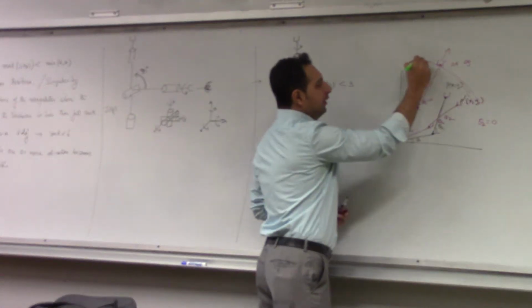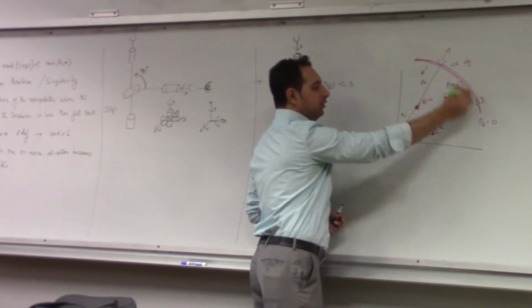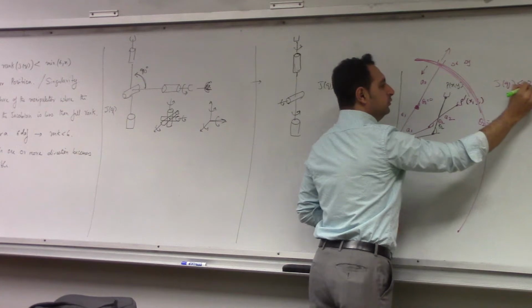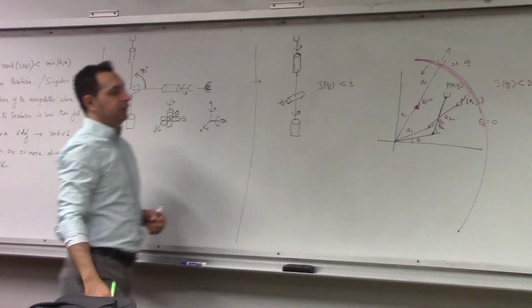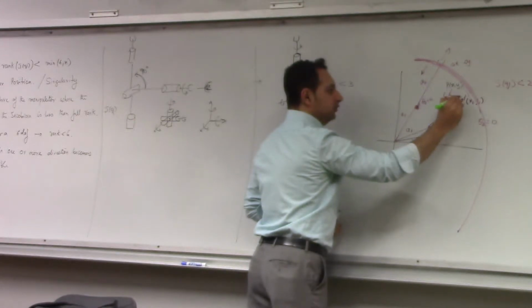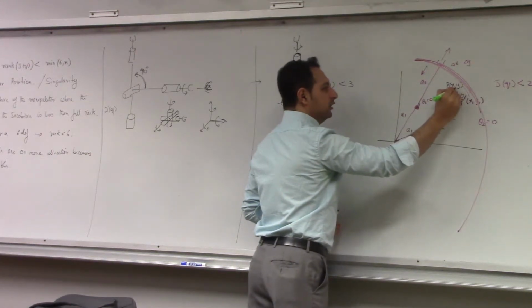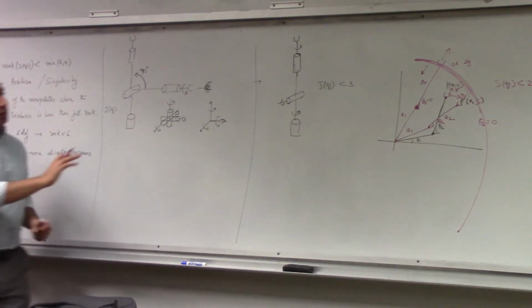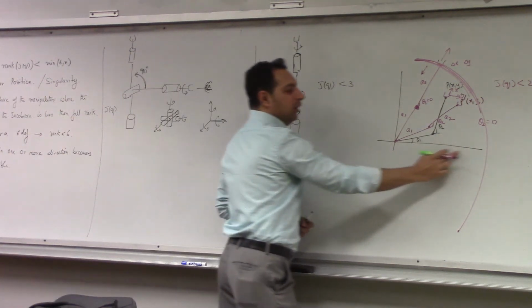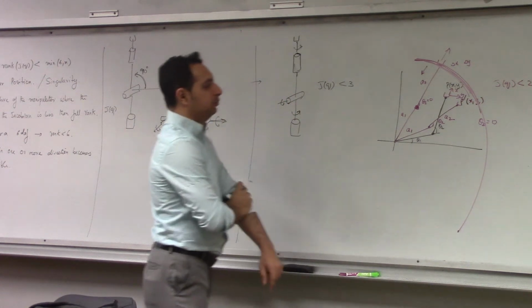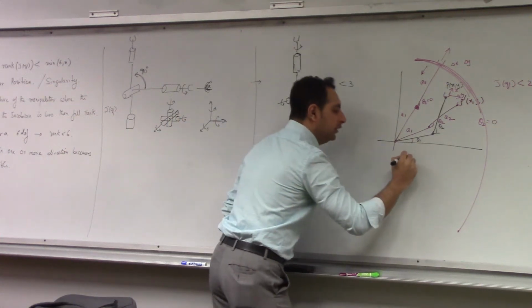So in this case, at the boundary of the manipulator, the rank of the Jacobian will drop to less than 2, because you cannot move in one direction. When it is within the boundary, you can move in both directions. You can move in x and you can move in y. It has full rank here. But in this case, you have lost it. So this is an example of an arm singularity. Anything that relates to positioning is called an arm singularity.